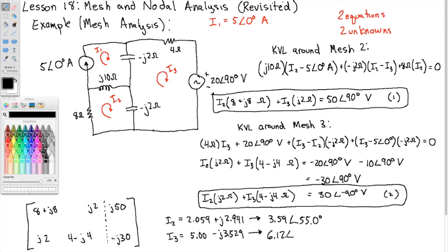And the angle of that number, again, you can use the command phase, and just remember that phase gives you back radians. So then you can use rad2deg. Okay, we get negative 35.2 degrees.